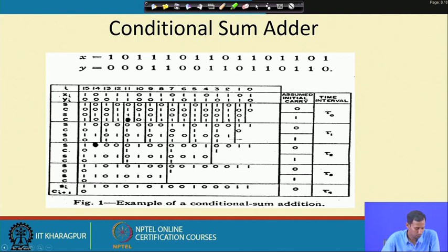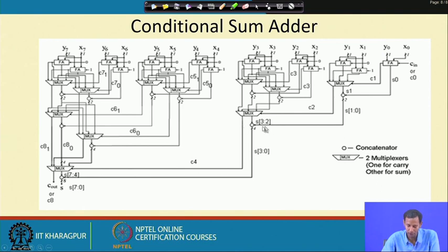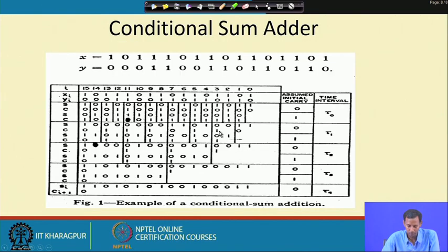So, the carry output bit or C 4 value is 1 here, and this S 3 is of 2 bit. Okay. So, here both of these are 0 and 0, so I will get S 3 and S 2 of 0 and 0. And for these two particular cases the sum is 1 and 1. Okay. So, now I am getting S 3 down to S 0 as 0 0 1 1.